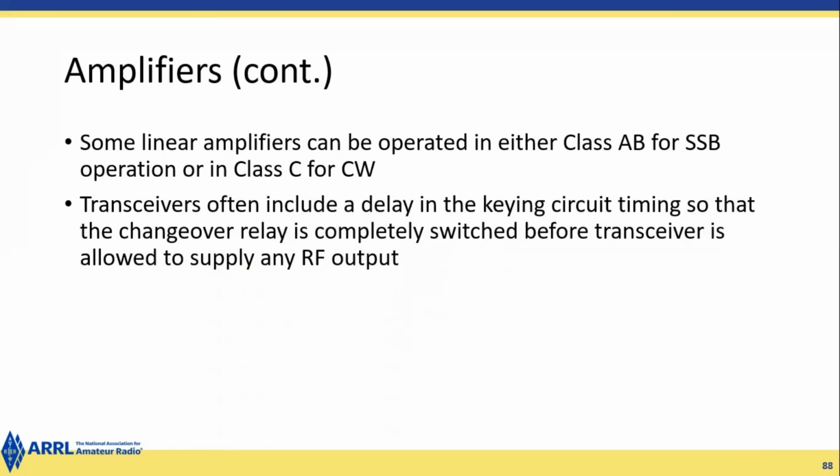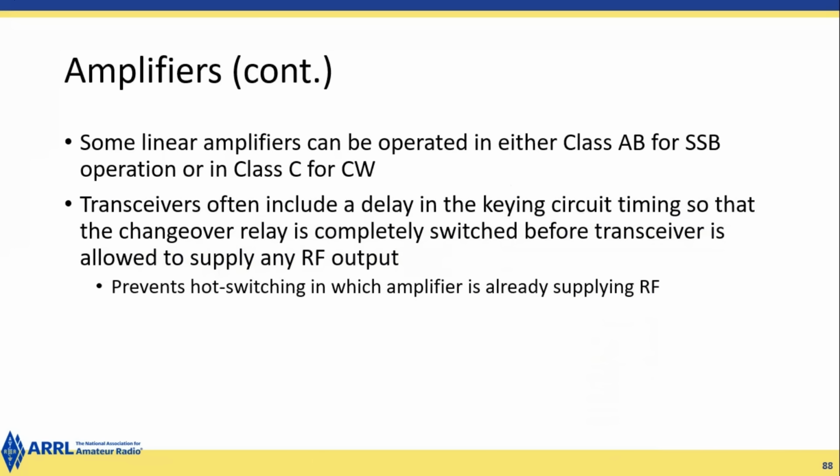Transceivers often include a delay in the keying circuit timing so that the changeover relay is completely switched before the transceiver is allowed to supply any RF current. This prevents hot switching, in which the amplifier is already supplying RF. It can destroy the relay or other external devices. Very important. You want to make sure you're switching between transmit and receive, and your amplifier is connected before you start transmitting.